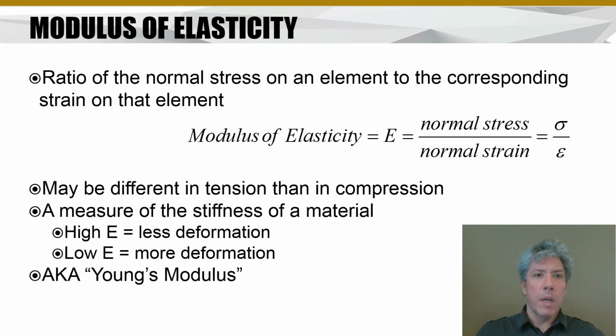Okay. Now let's go back for a minute and talk about linear stress and strain, so stretching something. In that case, we can define something called the modulus of elasticity, because one of the core concepts you need to get from this course is that we're interested in the force deflection relationship of everything. So if we use the ultimate tensile machines, what are we doing there? We're applying a force to a sample, pulling it apart, and monitoring the deflection, the response of it. That's really what we're interested in.